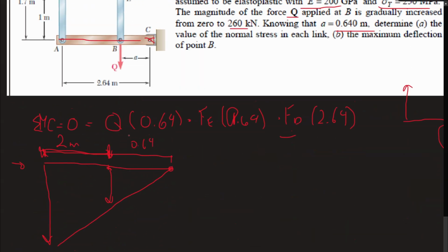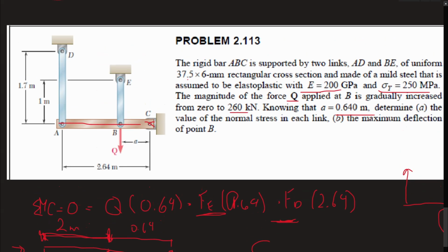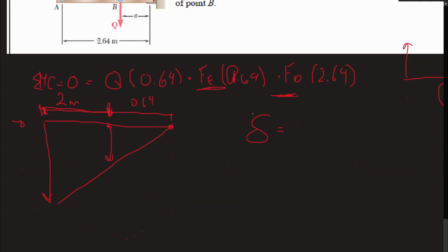This trick only works right now because I'm saying the forces are equal instead of their displacements. Normally you'd have to say the displacements are equal to each other and make another equation. But I know the forces are going to be of the same magnitude because the two bars are exactly the same. Oh wait, no, they're not. I have to make sure their properties are the same because they're different lengths. Ah, damn it. Okay, so I guess it's a few more steps.